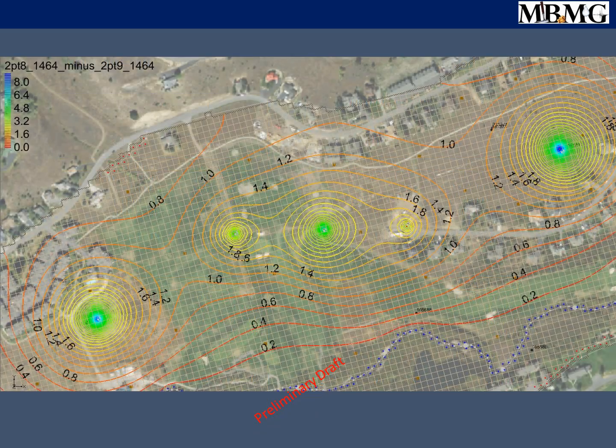So I've got one last element to show, and this is interesting because when you do aquifer tests on wells, you turn the wells on and run them full blast for a day, and then you shut them off and measure recovery. And groundwater hydrogeologists usually think that after 1 day of recovery, it should bounce back to where it started from.